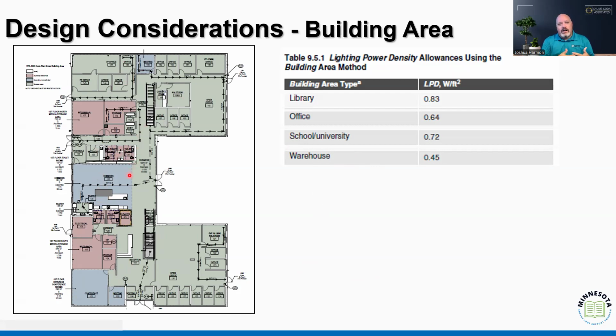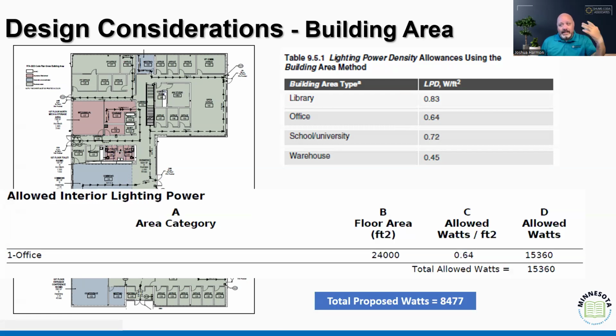So we can start to calculate different lighting demand based on different lighting area. Building areas get different lighting demand calculations. And so then I can calculate all of those based on square footage, come up to my value, and get an overall number. Now, what we saw in this one, this particular project, was they went with the simplified method.